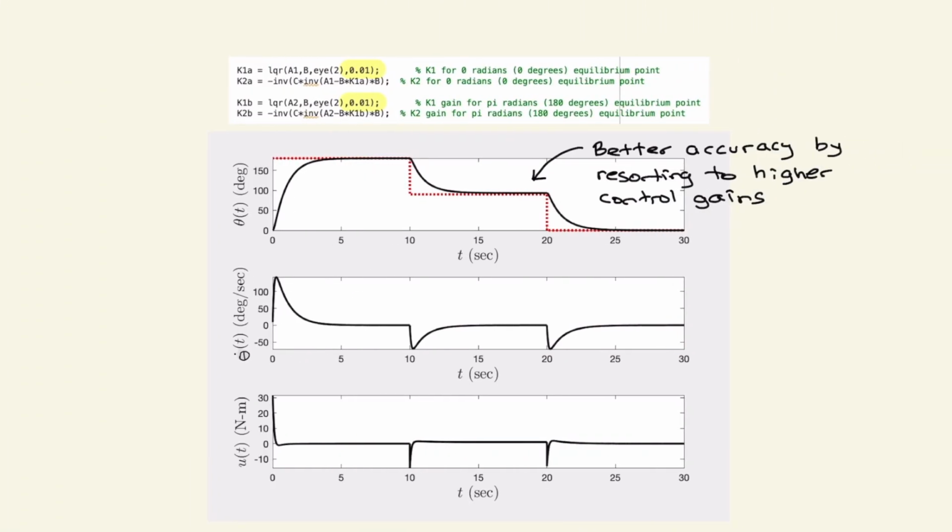So in the next one, I am decreasing R matrices from 1 to 0.01. So I am using a higher control. Decreasing R in LQR, linear quadratic regulator, basically will have a more aggressive control signal, higher gain.